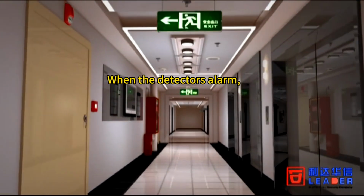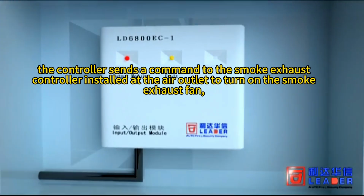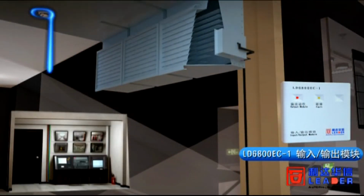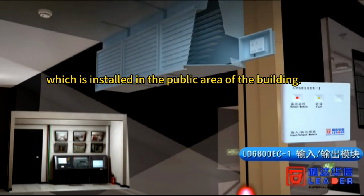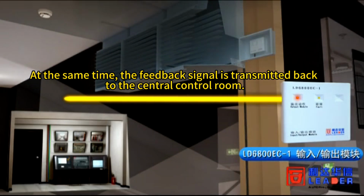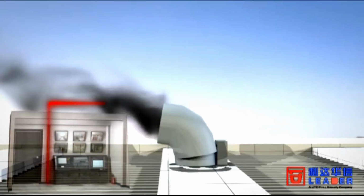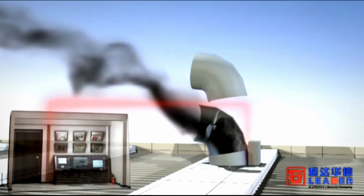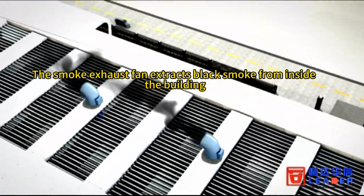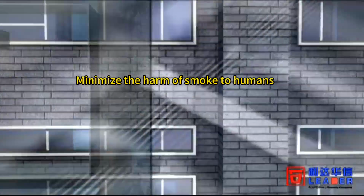When the detector alarms, the controller sends a command to the smoke exhaust controller installed at the air outlet to turn on the smoke exhaust fan, which is installed in the public area of the building. At the same time, the feedback signal is transmitted back to the central control room. The smoke exhaust fan extracts black smoke from inside the building, minimizing the harm of smoke to humans.